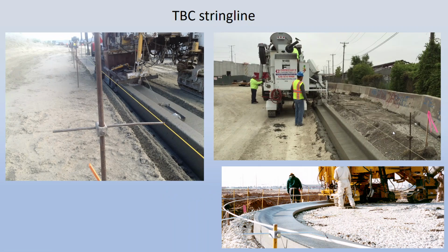And I just wanted to kind of break away from offsets just for a second here and talk about how curb and gutter is poured. Typically, it's done by setting string lines. So the contractors come through after you've set your offsets, and they set up these smooth bars, like a 5/8 bar, and they set this string line either at a prescribed offset or directly over the location where the curb and gutter is going to be. It all depends on how their machine is configured.